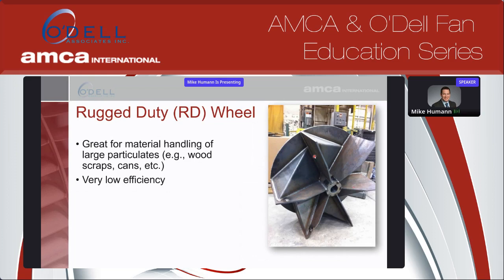If you're handling wood chips, wood blocks, cans, we even see aluminum slugs or aluminum trim handled. So certain wheels are really developed for certain processes, and there's a trade-off there. Obviously, you lose a ton of efficiency, and they can be very, very loud. But they do have their place in the market, depending on the application. But for a clean air application, this isn't something you'd want to select.